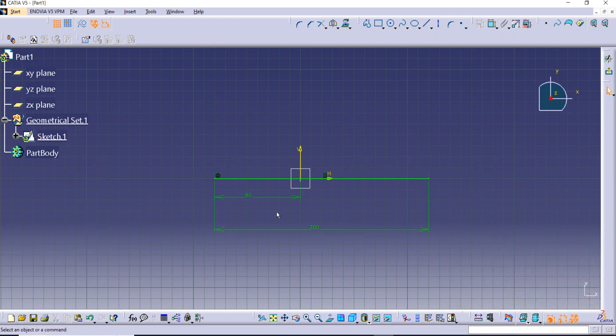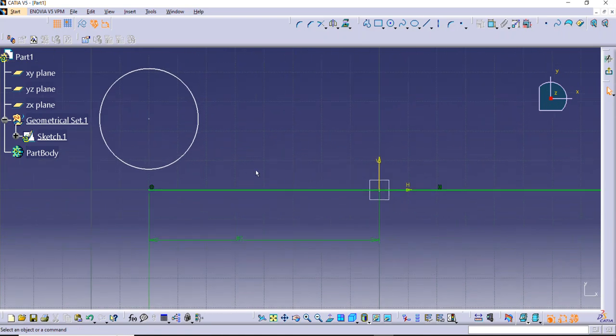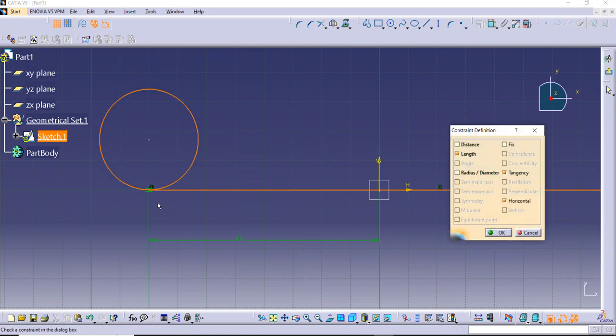Here in the wing section we are going to make a curve, a kind of circular one, and with the help of that circle we will work on it. Just make a circle here like this and align accordingly. If you observe, it is showing like this, but I want to make them tangent. So click on this, go here, and make them tangent. Here you can see the tangency is maintained properly.